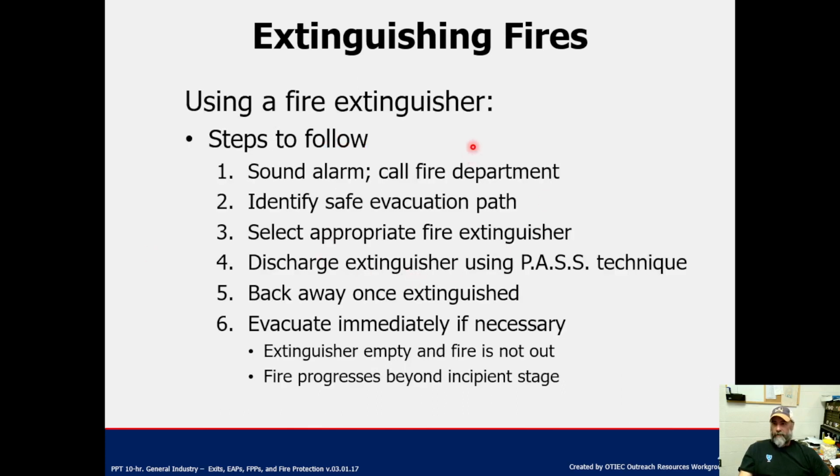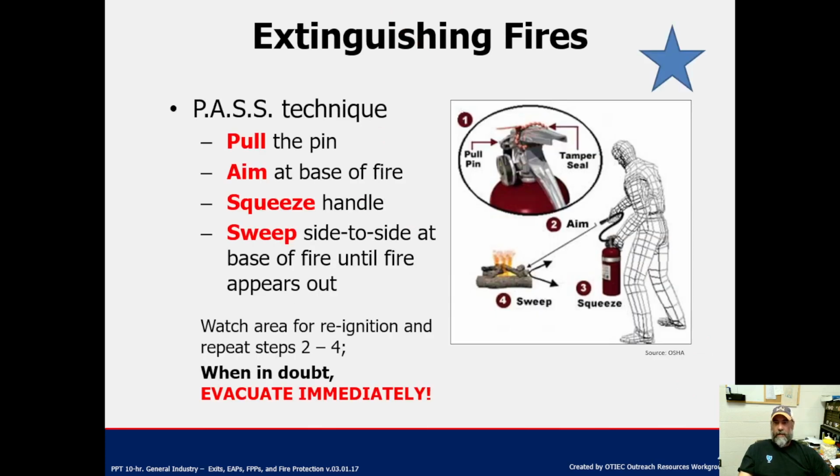Some of the different steps on utilizing a fire extinguisher. We see the PASS technique. If I go to the next slide here, we see instructions on the PASS technique. This is essentially how to properly use a fire extinguisher. Obviously, pull the pin. Sometimes you have to explain things, break them down into real simple terms. Pull, aim, squeeze, and sweep.